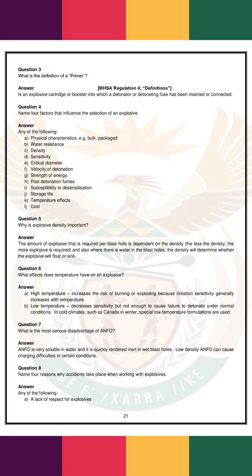Question 3. What is the definition of a primer? A primer is an explosive cartridge or booster into which a detonator or detonating fuse has been inserted or connected. Question 4. Name 4 factors that influence the selection of an explosive. Any of the following.